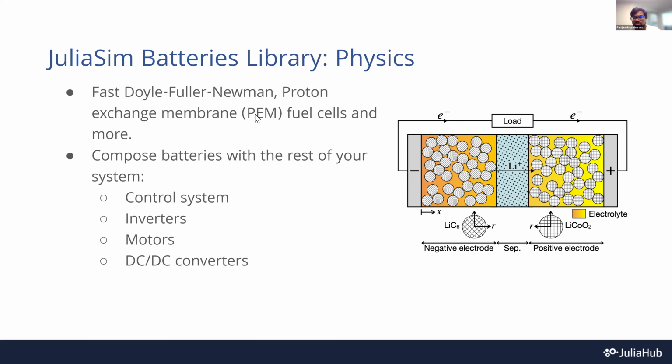To give you a quick sense of our battery models, we're building full P2D, full pseudo 2D, Doyle-Fuller-Newman (DFN) models, SPM models, SPMe models, physics-based models, and we can scale easily to packs and modules very quickly, and we are much faster than a lot of tools out there.